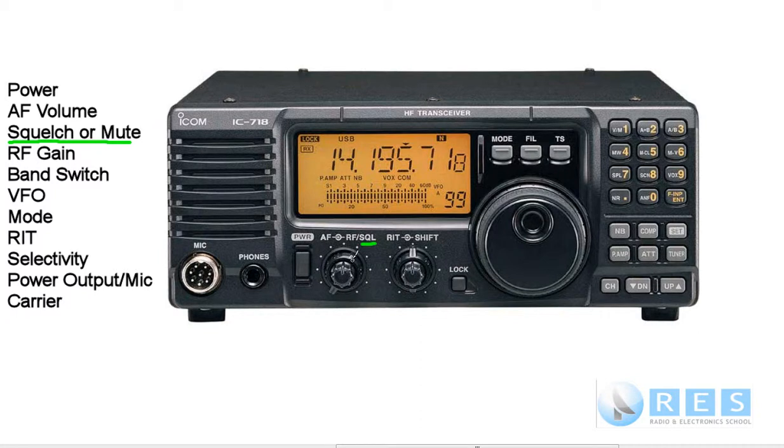We've got an inner ring, a middle ring, and an outer ring. And this lever here is the squelch control. So you'd rotate that in a clockwise direction until you heard no sound coming out of the receiver. So that eliminates the receiver noise when there's no signal present. Very easy control to use.